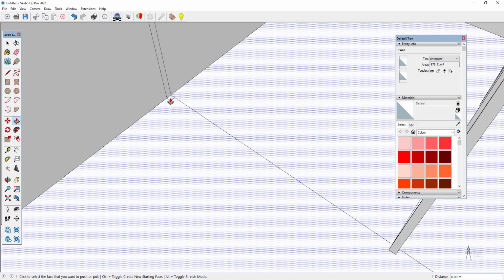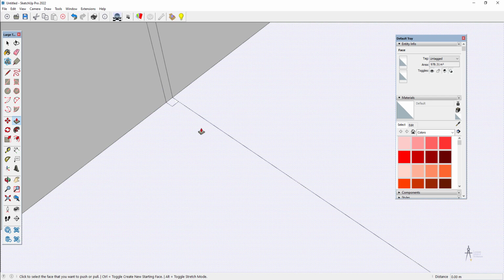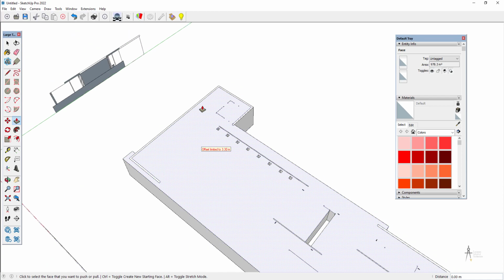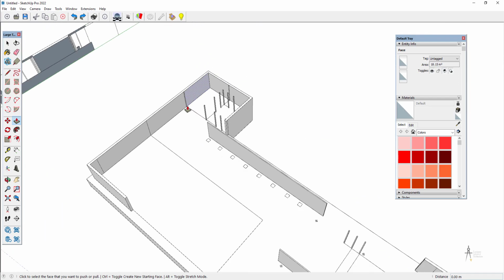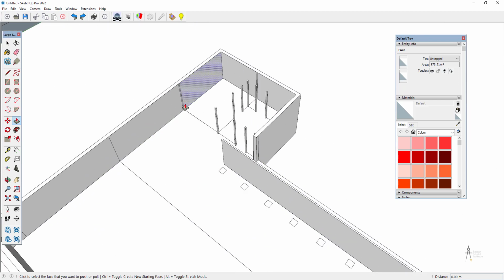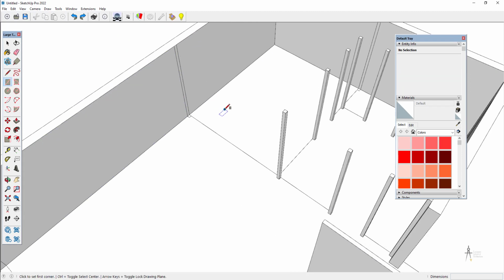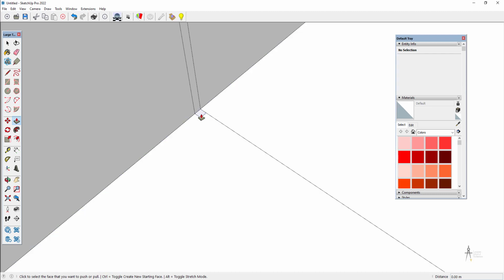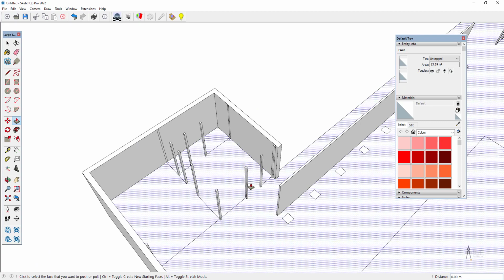So something that is going to happen is that some of these frames SketchUp is not going to recognize. So what you have to do, in this case, if I click there, it recognizes the whole floor, so it's lifted the whole floor. To avoid this, you can do a rectangle to do like an extra face, and now you click and double click, as easy as that.